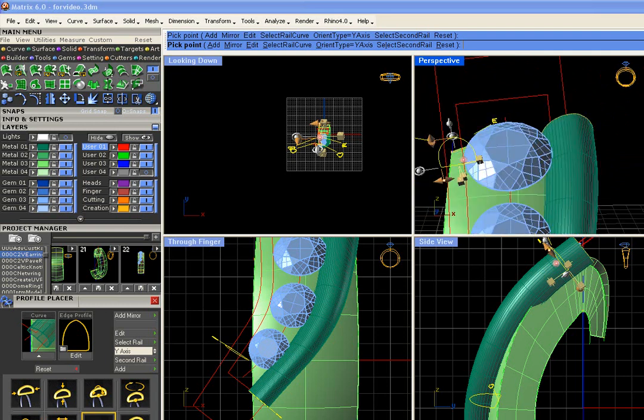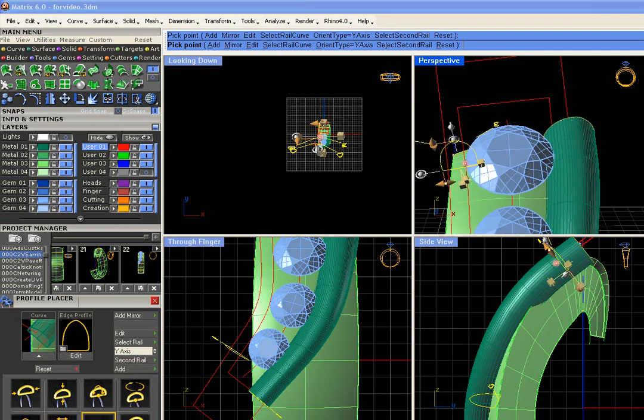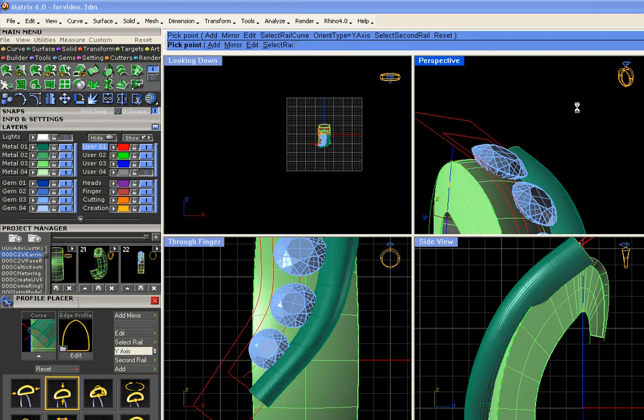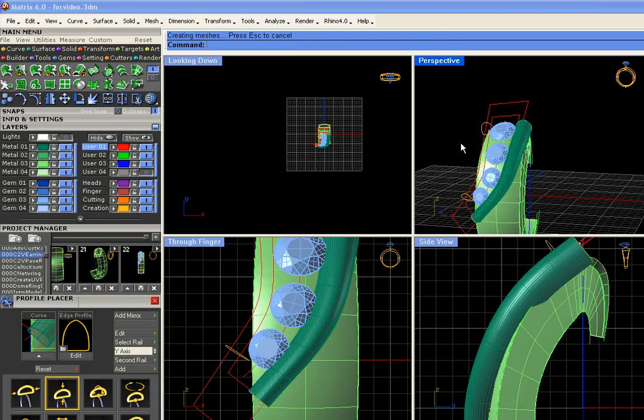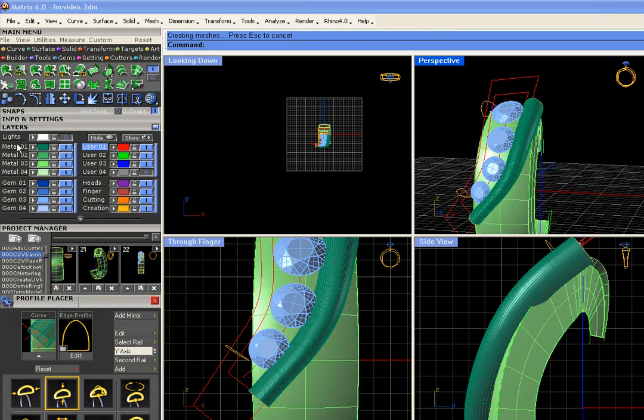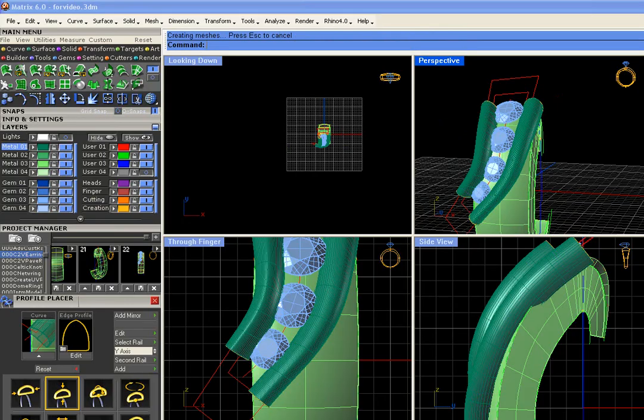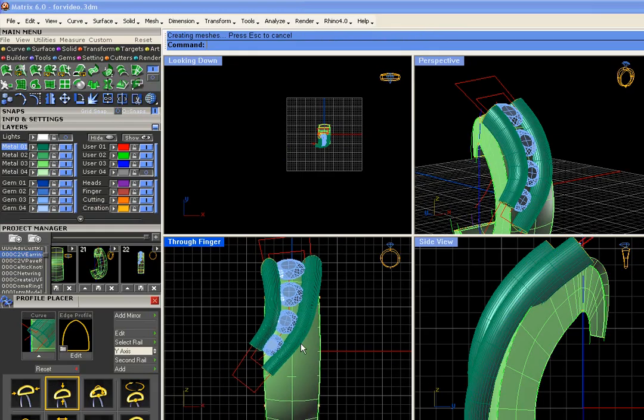In fact, if you wanted to, you could add from this one so that it was roughly already at the same correct size and stuff, but size and scale it. And of course with history we can do that again. Grab your metal color, sweep to history with the two rails, and make sure closed equals no, and the two profiles. Okay, there he is.